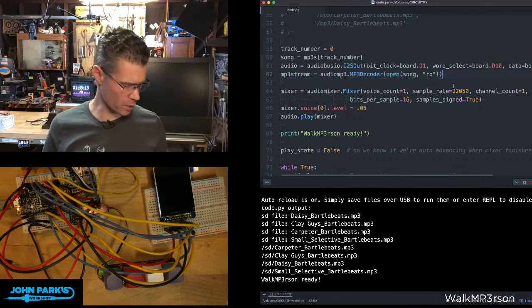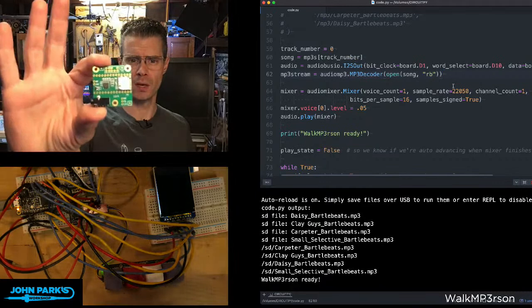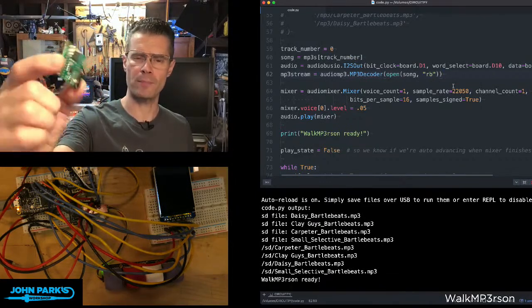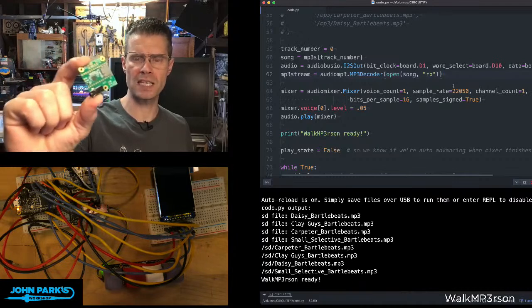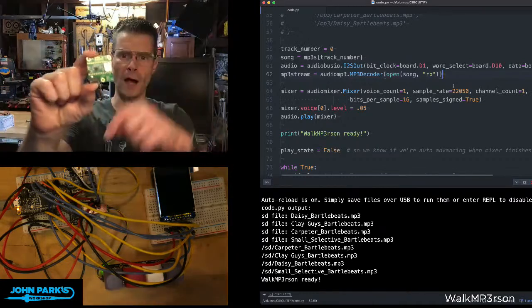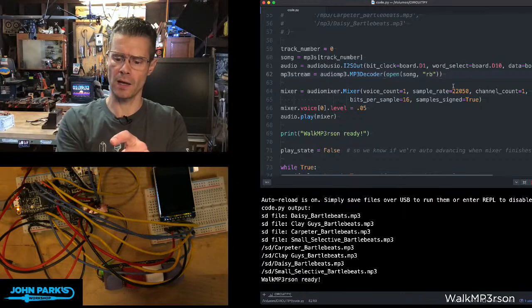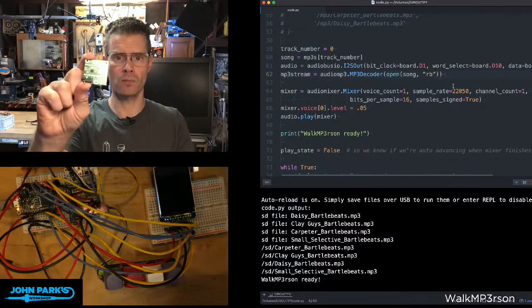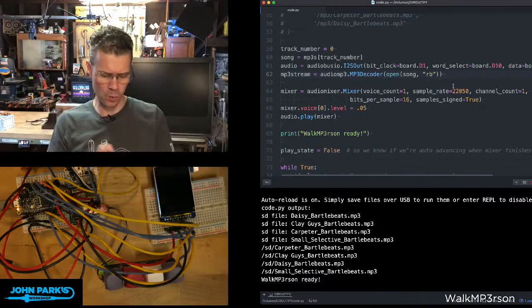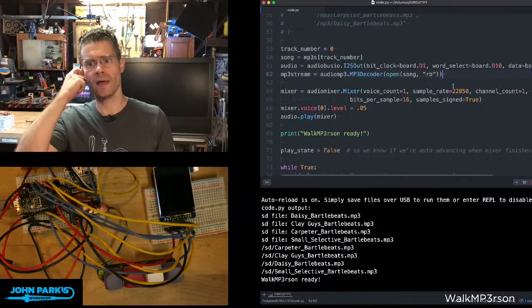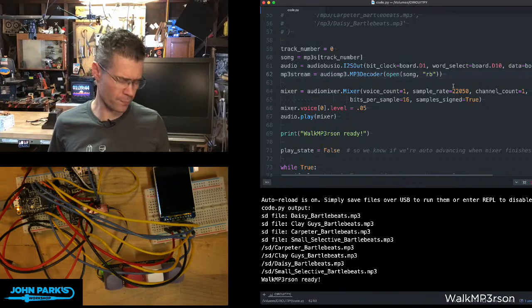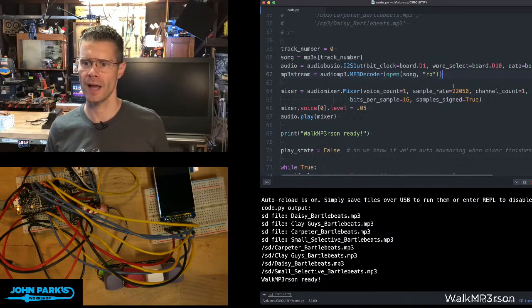I was trying to look and see, can I use one of these, which is the Teensy audio breakout adapter, or Teensy audio adapter. This is made for Teensy. It could probably be wired to run on other things. And it's got a nice little headphone out on there, and it has an SD card on it, so it covers a lot of the bases. But this one will not, as far as I can tell, work without having a master clock pin, and I don't think we have that worked out in our libraries. So for now, at least, that one's not going to work for me.